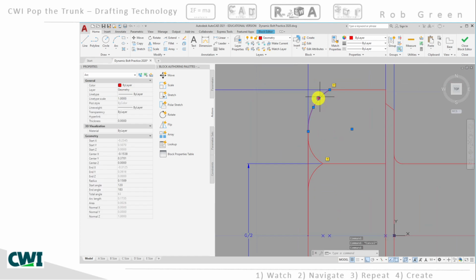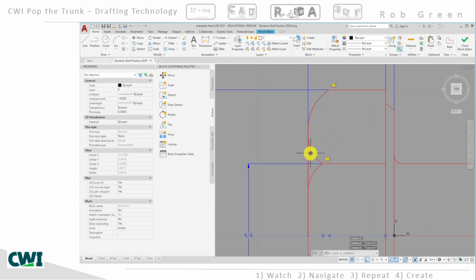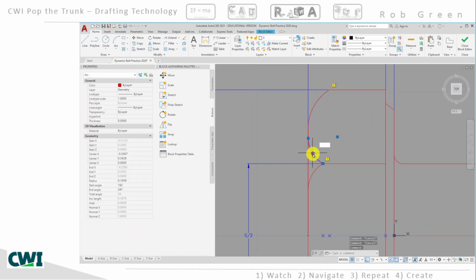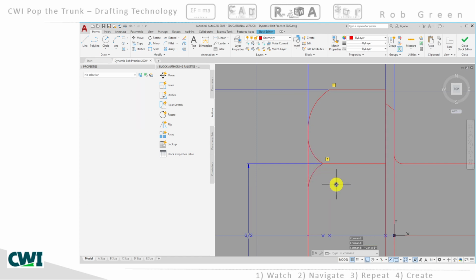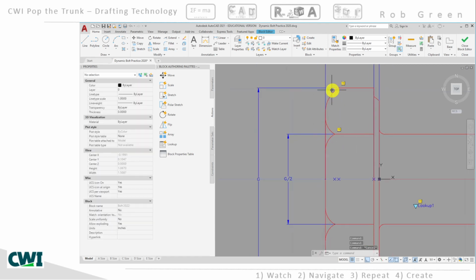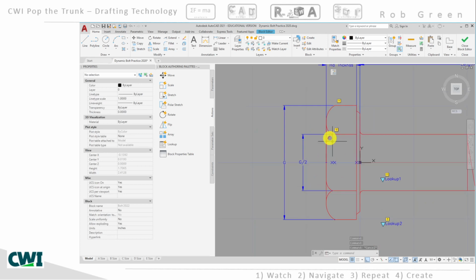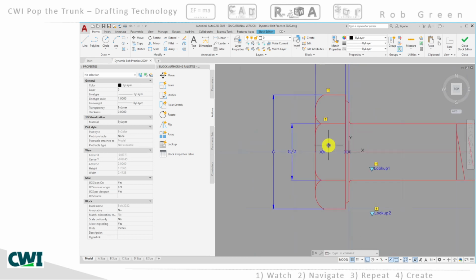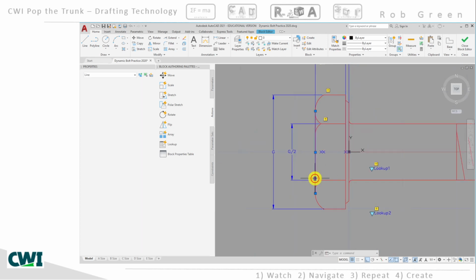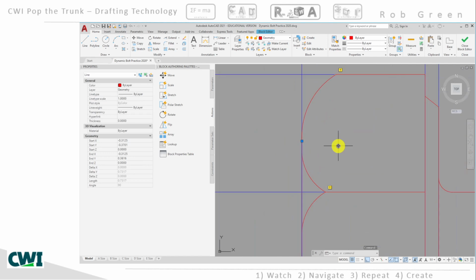So there's a 3-point arc drawn in here, and then there is an arc here that is the mirror image of this arc. So make sure that you have those as separate arcs. One more tidbit, this vertical line that's here wants to end at the end point of this 3-point arc.